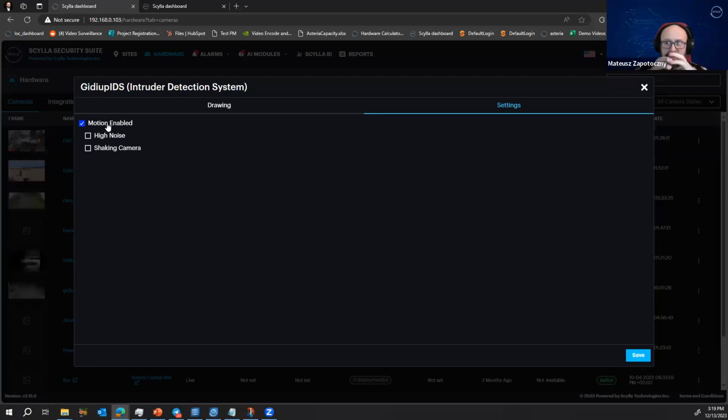This module, this AI module inside the camera, it's not doing the analytics on the mainstream of the device. Usually, even if you have the camera that is full HD, 4 megapixel or 4K, it doesn't mean that the analytics are working on the 4K stream. There is internal stream with lower resolution that it's being analyzed. In our solution, it works differently.